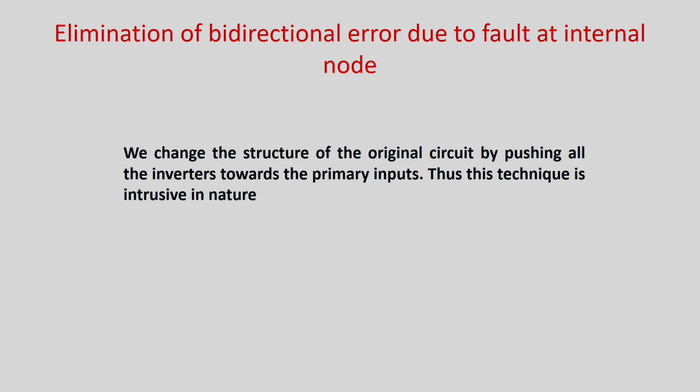So there is a lot of tussle between the test engineers and the designer. How much intrusivity will be allowed? I am a designer. I have given a circuit which is optimized in area, timing, and power. The test engineer is changing a lot of the design in my circuit. I may not like to do that, and in fact the changes allowed to the test engineer are very minimal. So therefore, in the modern community of online testing, these error detecting codes are not that much accepted.